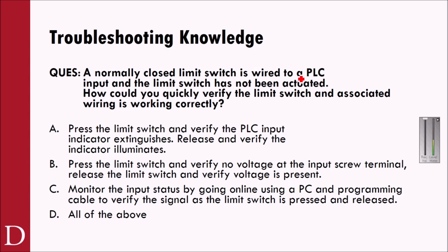So we've got a limit switch. I'm going to go over here. We've got a normally closed. So it's going to look something like this. I've got it drawn kind of backwards here. There we go. So normally closed limit switch, as I press it down, it would open, right? But it's wired up to my PLC input.